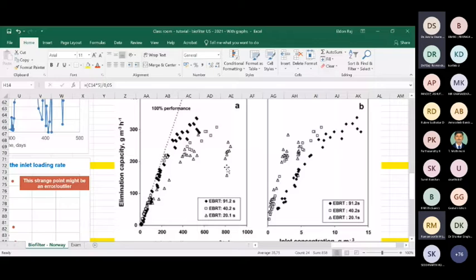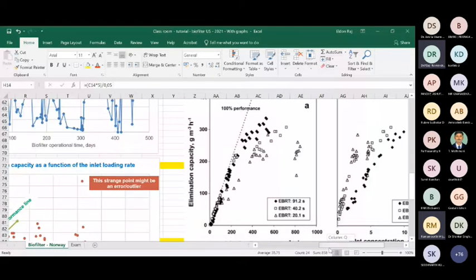As I had mentioned to you, a biological system is often limited by its kinetics, and it always has its maximum capacity to biodegrade any organic pollutant. And this is, as we all know, not a physicochemical process or an advanced oxidation process where you can go up to very high loads. In a biological system, the process is slow and governed by different factors, and that is why you have to know what the limits are and what we can do to make sure that the system will operate well within the design limits.